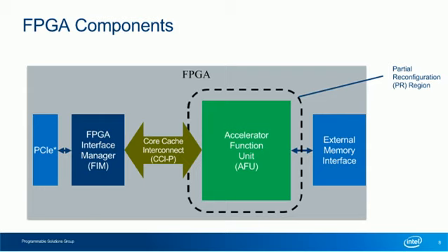This allows the FPGA hardware to reconfigure the AFU bitstream accelerator functionality. When using a discrete FPGA on a PCIe board, the AFU will also have access to external memory controllers, which are connected to off-chip memory, such as DDR4 memory.